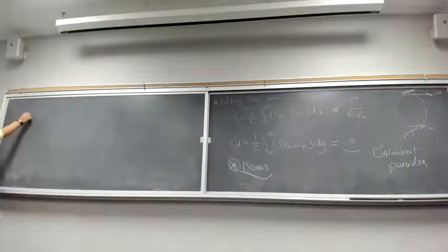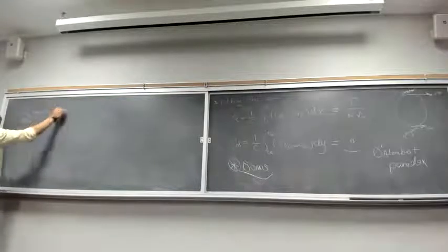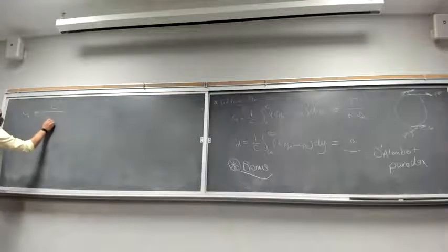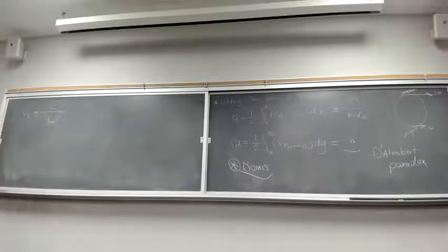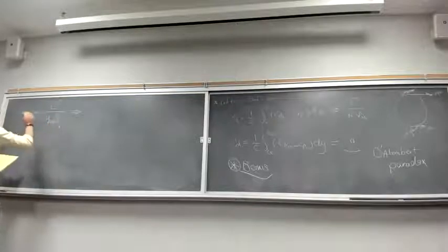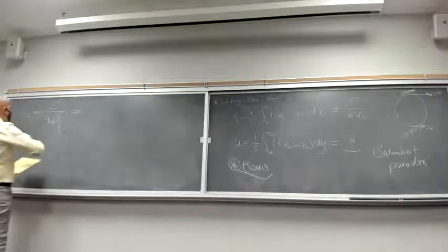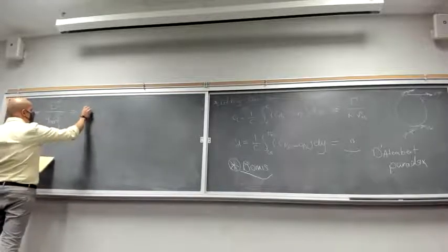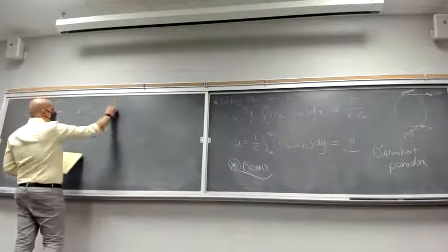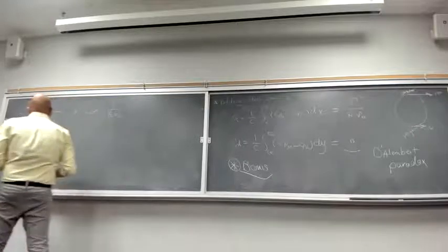We are dealing with lift, and it's a two-dimensional thing, so we're going to use L prime, lift per unit span, over Q infinity S. Here you're dealing with lift per unit span, so your S is R, only R. We also have another formula for CL, gamma over R V infinity, right?